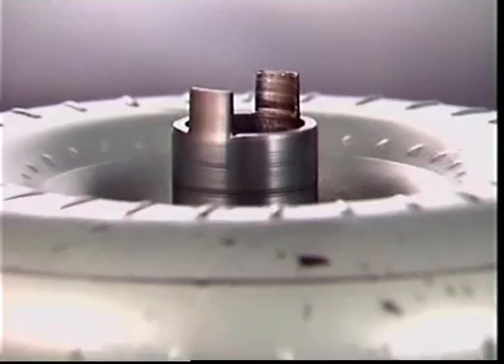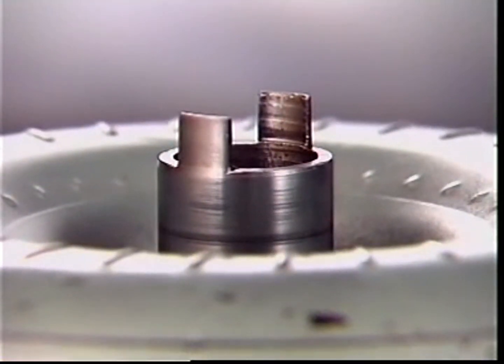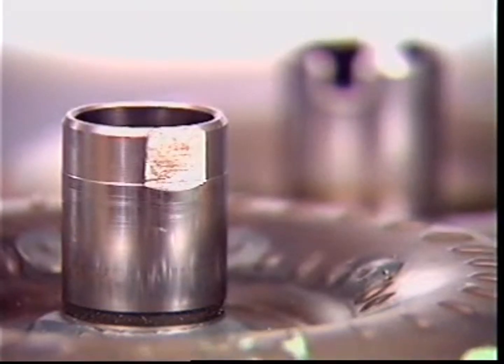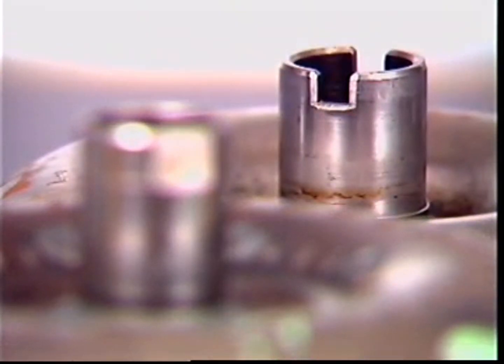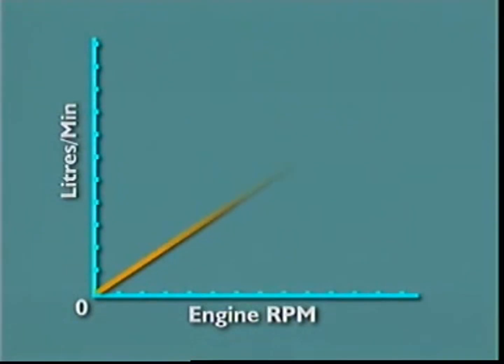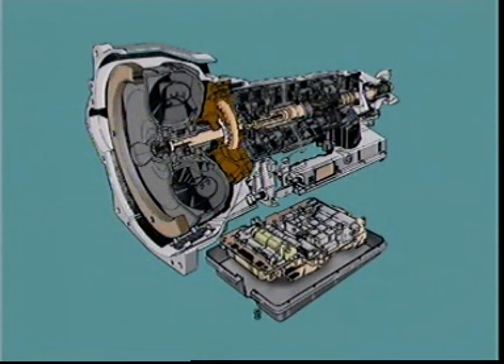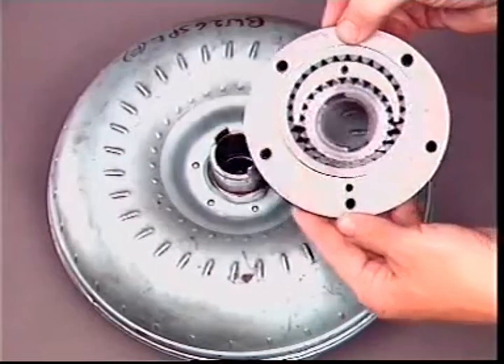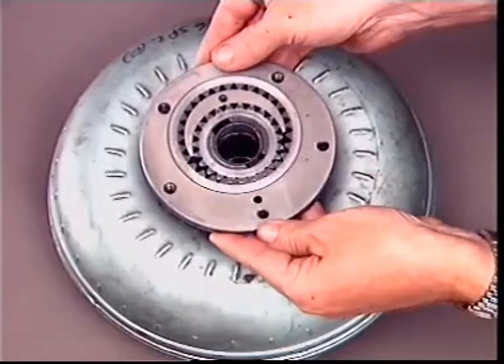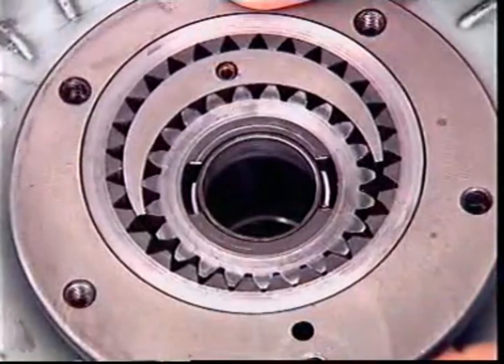The pump driving member is engaged by tangs on the converter spout, or machined flats, or by slots. Pump output always exceeds normal operating demands, so pressures are controlled by regulating valves. Excess fluid returns to the pump inlet or is dumped into the oil pan, where it can reach the pump intake strainer. Crescent-type pumps are commonly used in automatic transmissions.